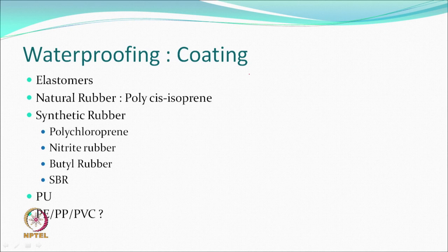And then other polymers which are relatively low glass temperature, but not necessarily as low as, let us say, natural rubbers and synthetic rubbers, also can be used to make waterproof materials like PVC, polyethylene, which is a softer material, can also be somehow applied onto the textile to make them waterproof.